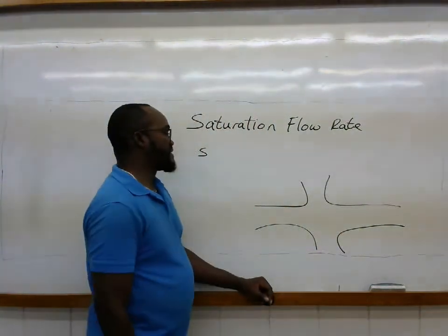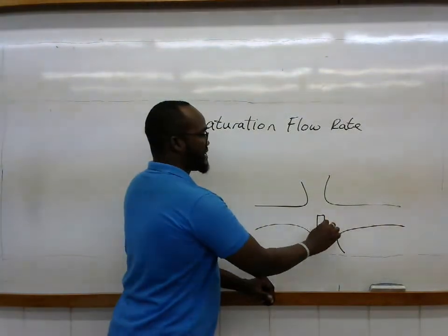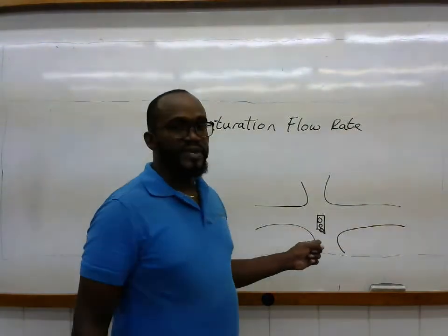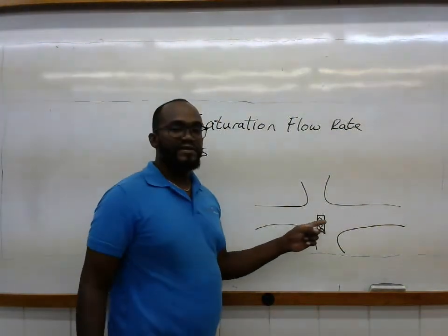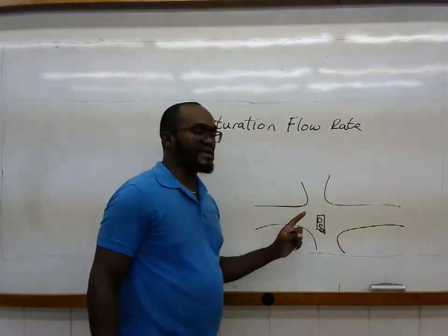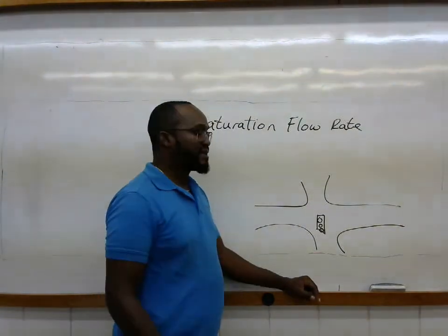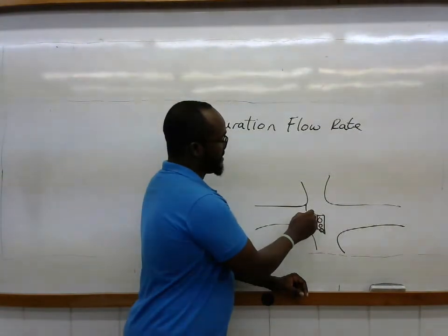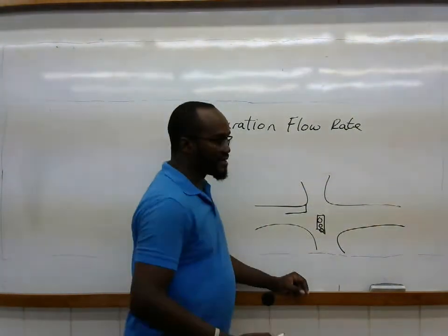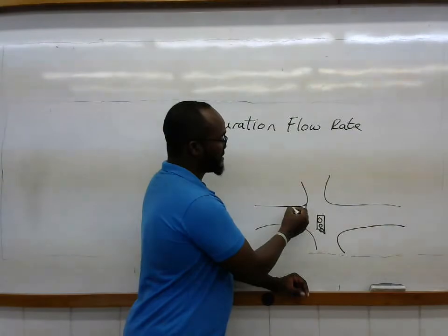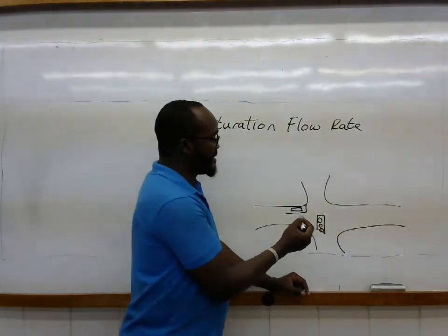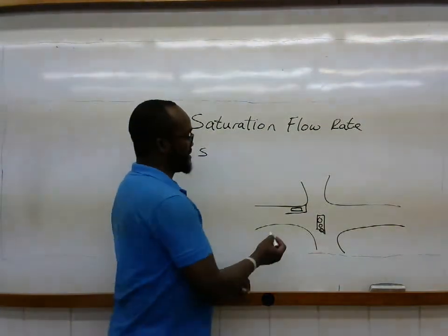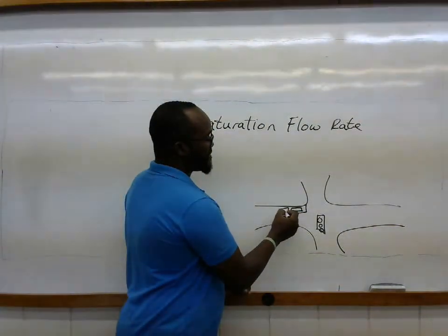So we have our signalized intersection. But obviously, we cannot determine saturation flow rate in the field because there's no intersection known in this world that will have 1 hour of continuous green. So, in order to compute the saturation flow rate, a compromise must be made. And so, manually, as some of you would have done in the field, the saturation flow rate would have been computed